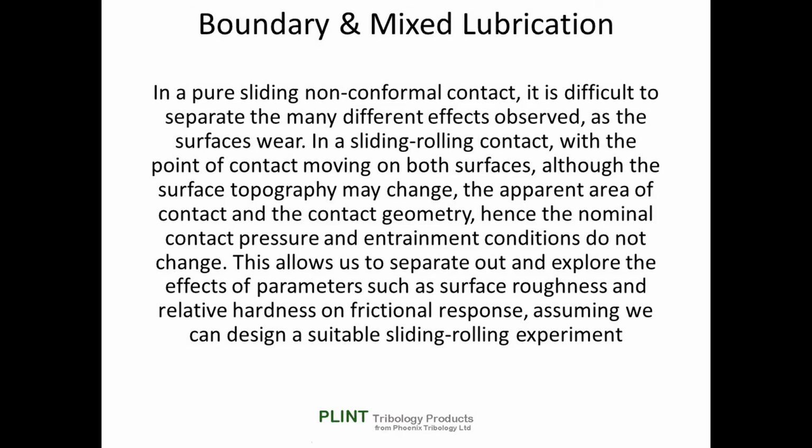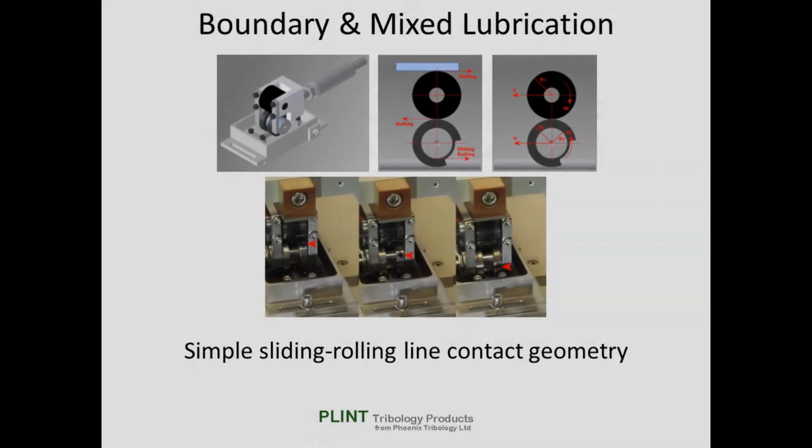hardness. This adapter was designed specifically for this purpose and uses a simple and low-cost roller specimen running on a flat rail. Two discs are secured to the roller by grub screws, with the inner faces of the discs locating on either side of the rail, providing axial guidance.